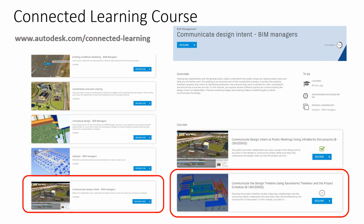Okay, so Don Pecura is asking the question, what is actual and planned? Is actual modeled or point cloud? I'm not sure I understand the question there, Don. Actual and planned just really means that we had a plan to build a foundation starting on the 1st and finishing on the 5th, but we started late because the groundworks were not finished yet. So the actual dates were, I don't know, the 2nd, and then the end was the 7th. So Navisworks allows you to show a simulation separately, one for how things were planned and how they're actually being done.